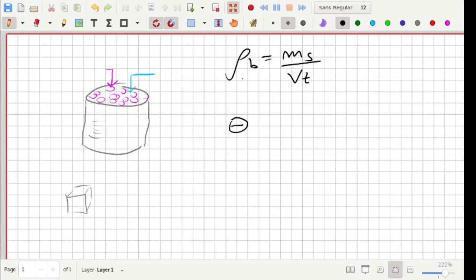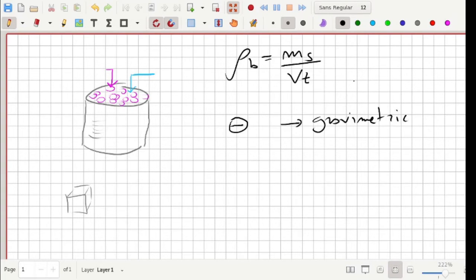So you have two types of water content. You have a mass-based water content, which is usually called gravimetric. It's mass over mass. In fields other than soil science, this is usually represented as a percentage, but in soil science it is usually represented as mass over mass, so grams of water per gram of dry material. We don't usually cancel the units here because we're talking about different things.